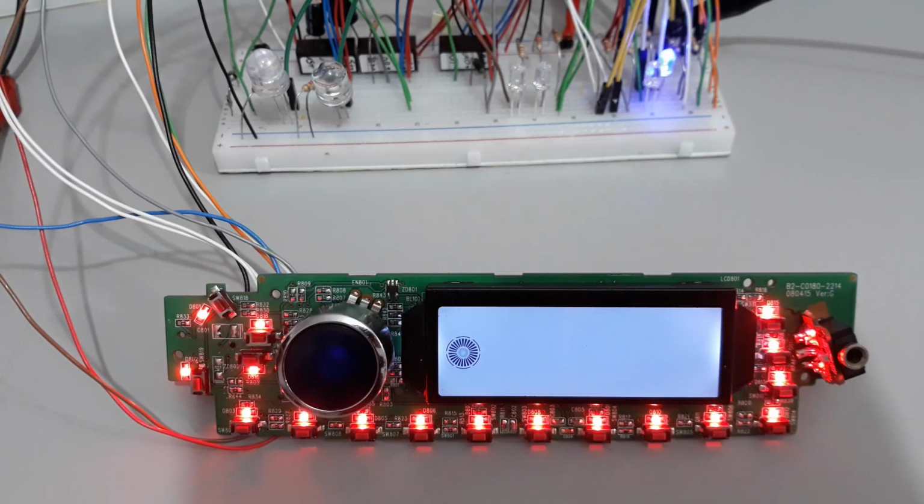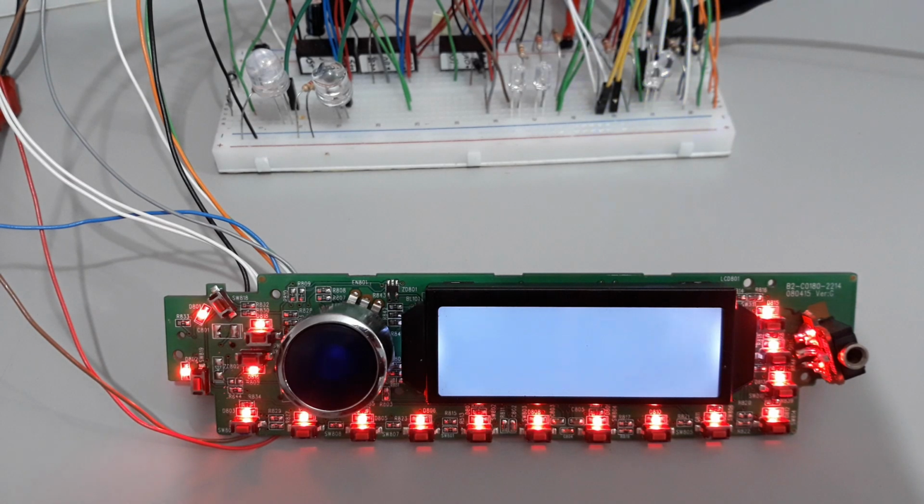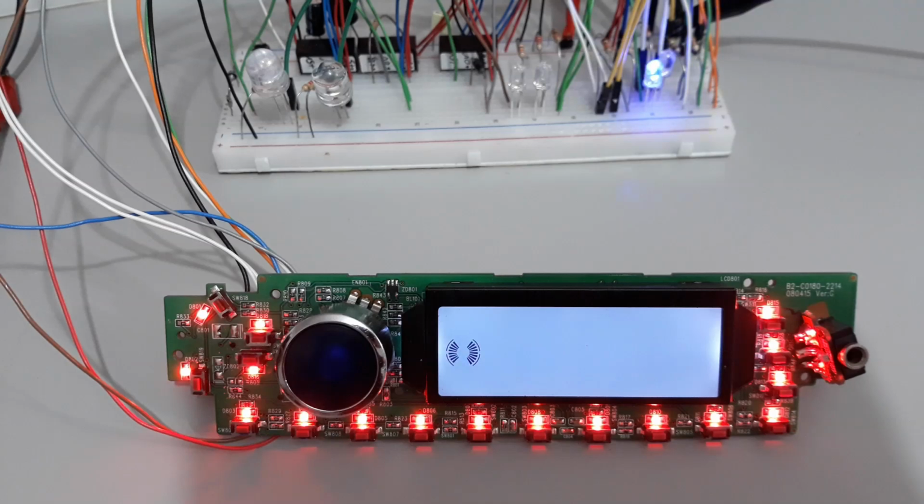The rotor knob, in particular, has a curious and unusual use. Being a quadrature rotor knob, one would expect its use to be in that sense, but no. It has two resistors, one in each phase, which in turn converge to a common point, allowing reading only the rising and falling sides of the same point.